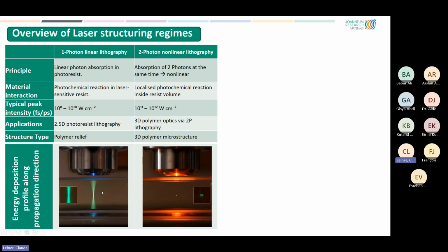The next thing is when you're increasing the peak intensity of the laser. So this you can do in continuous laser writing. This is already pulsed, and then you are compromising the intensity in these pulsed peaks, let's say. Here you can use two-photon lithography. This is already a non-linear process. Here you can see this is just a beam, and you can use it at every slice here as you want.